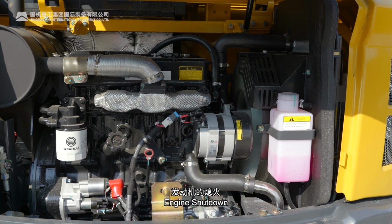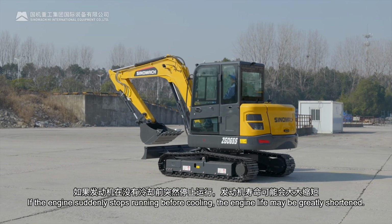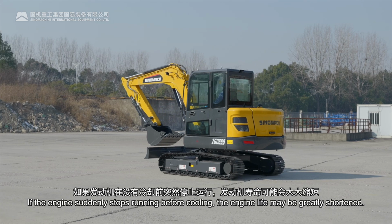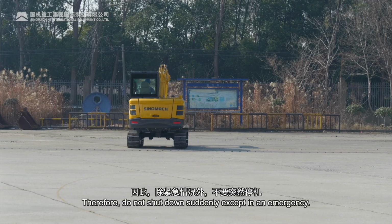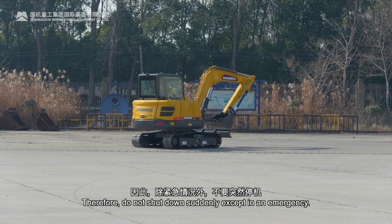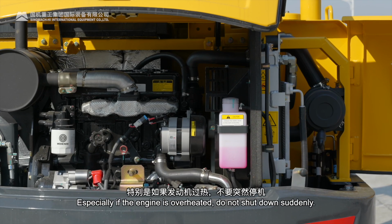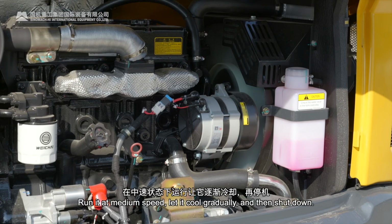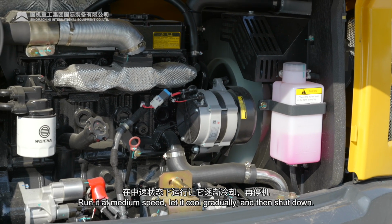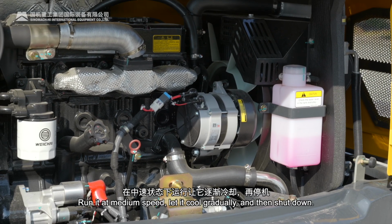Engine shutdown. If the engine suddenly stops running before cooling, the engine life may be greatly shortened. Therefore, do not shut down suddenly except in an emergency. Especially if the engine is overheated, do not shut down suddenly. Run it at medium speed, let it cool gradually, and then shut down.